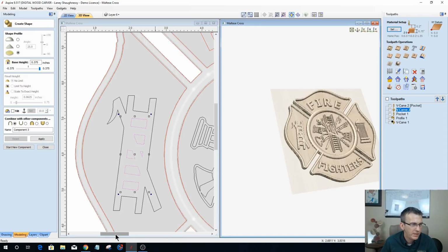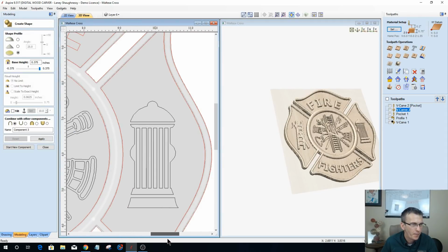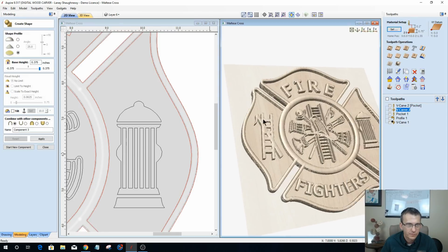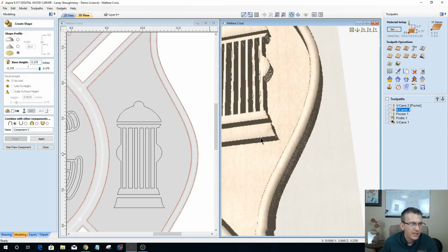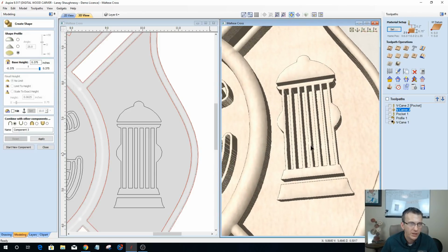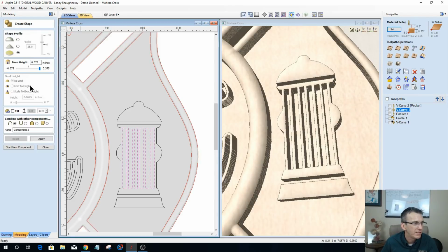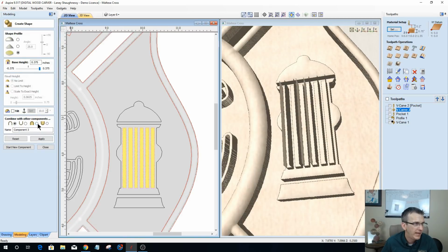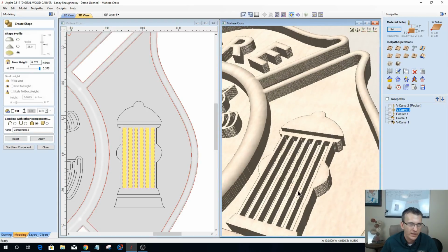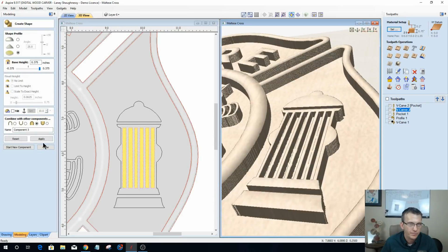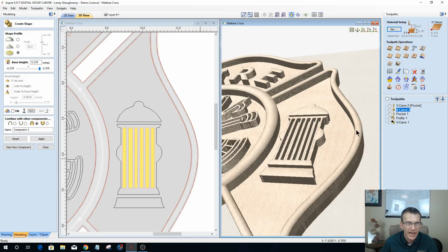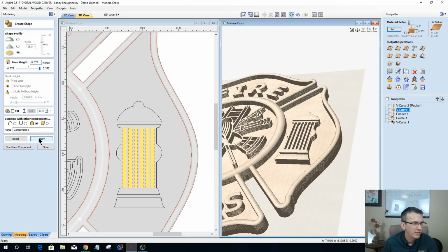Let's go over here to the hydrant. I'll do the middle one last. The hydrant, just on the inside of my fins here. So these guys here, I want to do the same thing. Click apply, and it's going to be a merge, not an add, merge. See what happens when you add it, it puffed it all the way up. And all I'm doing is just filling in that meat a little bit, enough. Now, don't worry about these straight walls. We're about to add a draft. I'm going to talk to you guys about adding drafts to your models here in just a second.